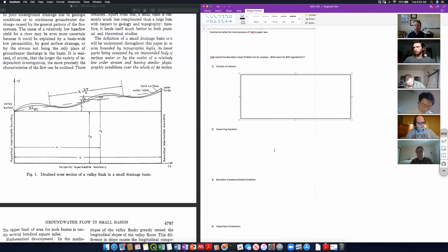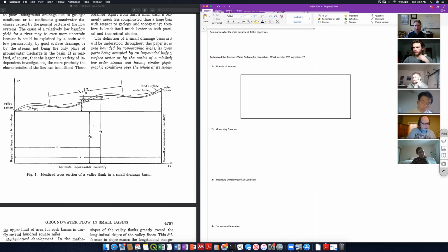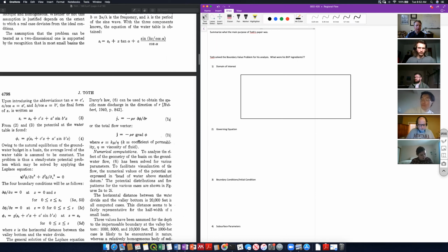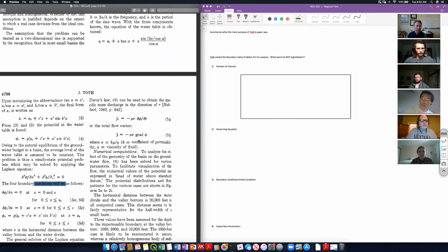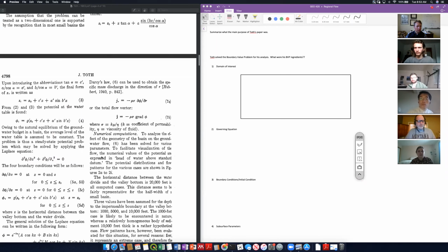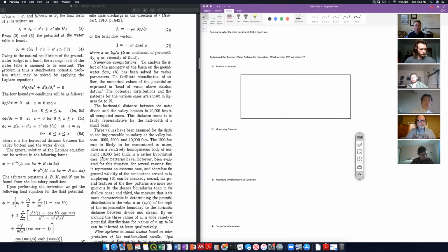All right, were you guys able to see what his governing equation was? Yeah, it was ugly. Well, the actual governing equation was not. Yeah, it was just a 2D Laplace for head, right? Yeah, this is it right here. So here's the governing equation. Let me highlight it. And it's this guy here. It's the Laplace equation for head. Oh, it wasn't number 6? Number 6 is all the way down the bottom of that page. That's a solution. Number 6 is the analytical solution.